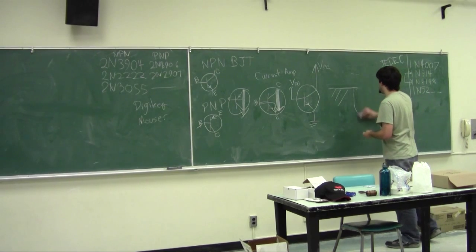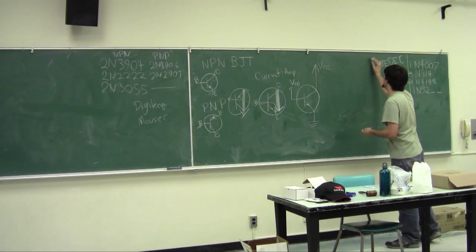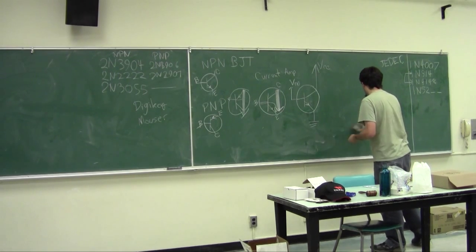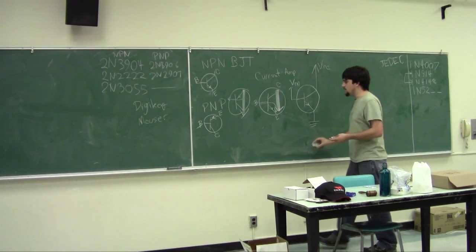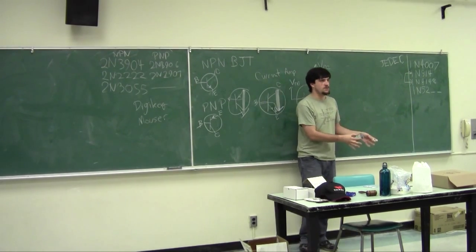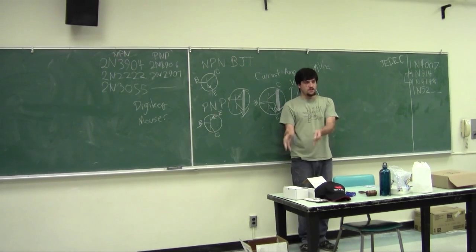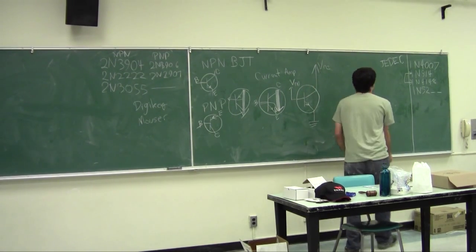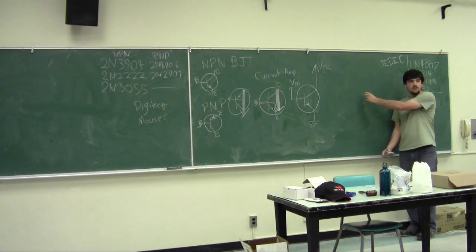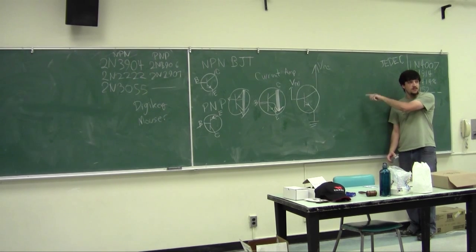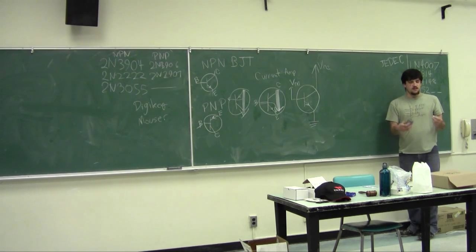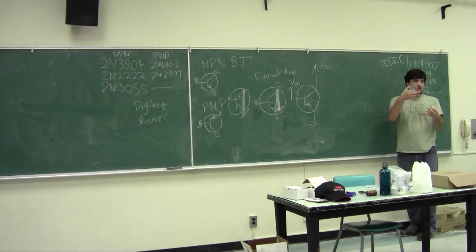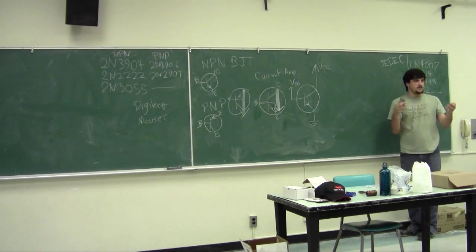Of course, in their infinite wisdom, scientists decided not to just invent one way to use semiconductors to amplify things, but many, many different ways. They kind of all divide into two categories. Your bipolar junction transistors, like this, and your field effect transistors. Instead of the gain being based upon the removal of that depletion region via the current through the middle, as you can see here, field effect transistors instead depend upon the static electric field being applied to a semiconductor to create or destroy that depletion region.